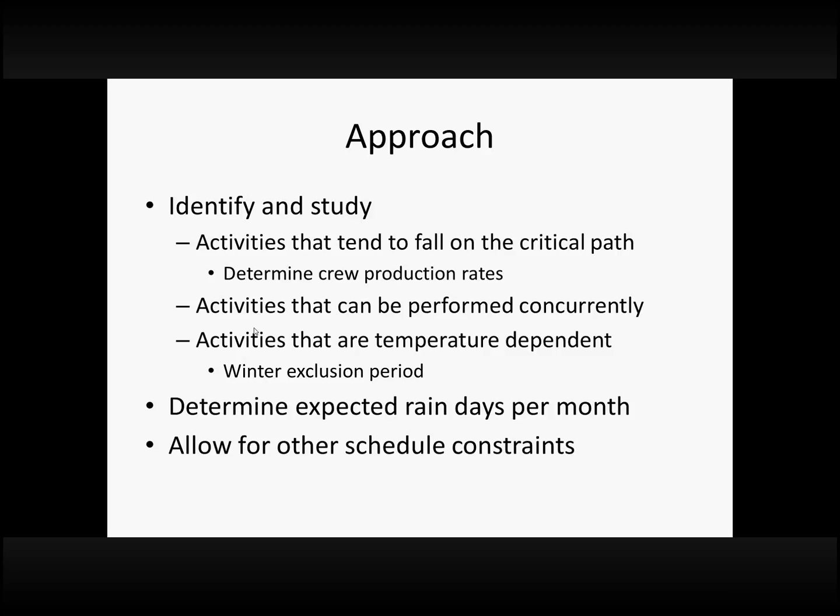Especially for a larger job, you would have a larger crew or more crews, and some of that had to be considered. Most of our templates just look at a series of activities, one after the other, but we do look at some places where activities can be performed concurrently. Obviously, you can get done faster if the scheduler plans that. And again, we identified the activities that were temperature dependent based on the IDOT specifications, and used that to help define, based on the location of the project, when the likely times would be that they could do those activities and when it wouldn't be.